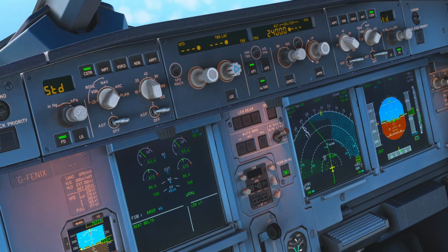Open climb and open descent are used to climb or descend to a new altitude. The pilot will pitch for the target airspeed. Auto thrust commands either climb thrust or idle thrust. Rotate the altitude knob to set a target altitude. Pull the altitude knob to activate the open climb or open descent mode.